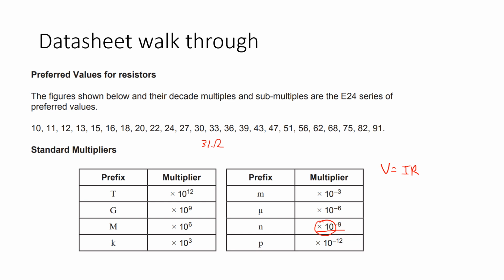It doesn't say that happens all the time, but if you had something like, let's say, 10 volts and 2 milliamps, then I can go R equals V over I. So in my calculator, I can just go 10 over 2. I'm not going to put 2 times 10 to the minus 3, because I know that if I've used milli there, it comes out in kilo ohms.